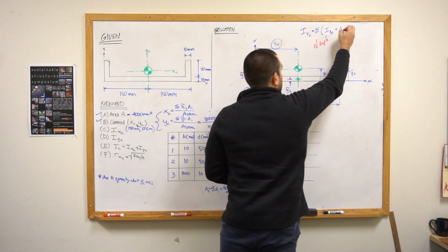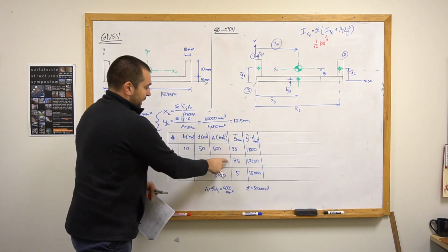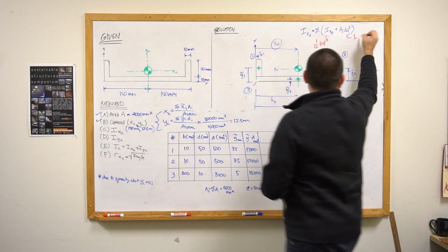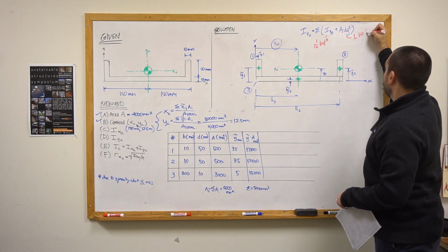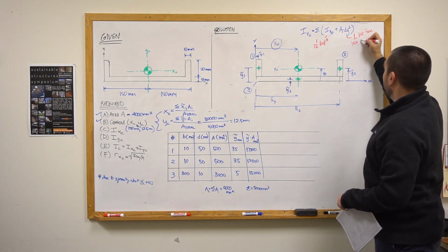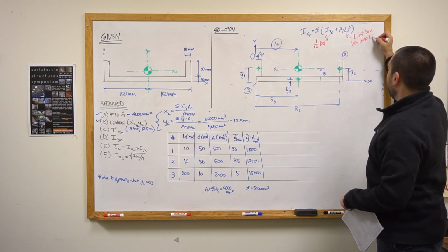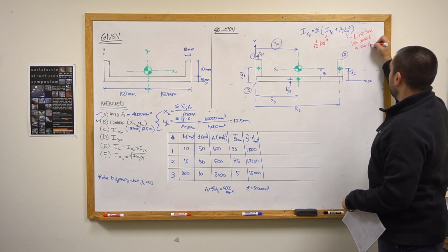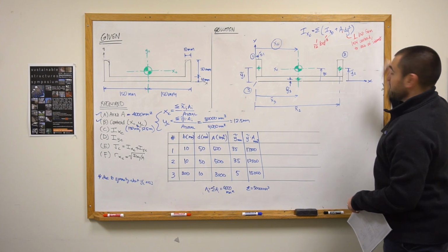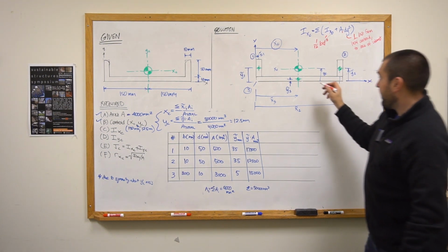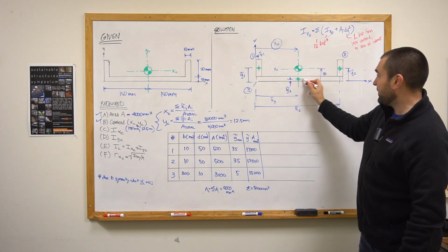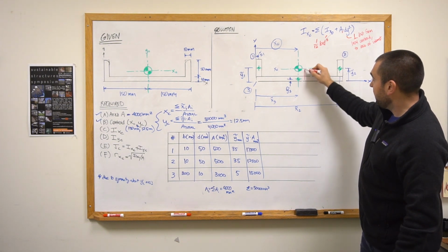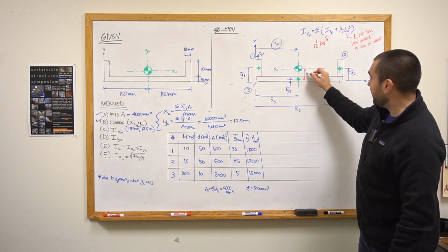The area is just simply the area of each individual shape. We have that in the table here already. dy is the perpendicular distance from the local centroid to our axis of interest. So if I were to draw that distance for shape 3, here is the local centroid, and the perpendicular distance from our axis of interest looks like this. So that's this distance. This is dy sub 3.